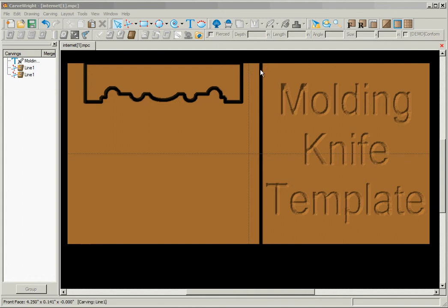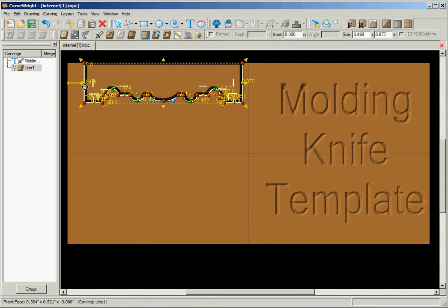This line up and down the board is just where he cuts off his material so that he has the template equally spaced within his section that he keeps. So first thing I'm going to do is get rid of that line. Okay, now we're going to work with this line, and if you look at it, the radius on the left here is a 0.124, and what he has on the right is a 0.121. He's got some constraints we're going to deal with first.